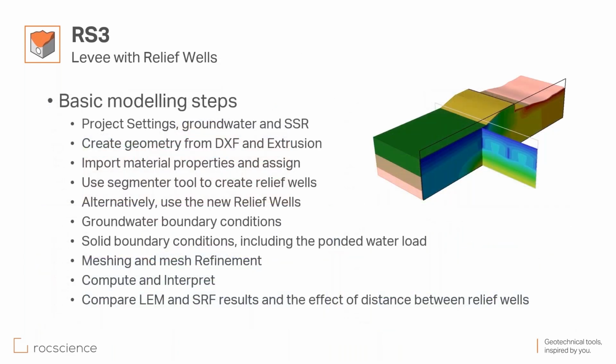These are the steps that I actually took to generate that model before, to analyze for seepage analysis. We will look at project setting, create the geometry, use Segmenter to generate those relief wells, or alternatively, I introduced the relief well entities that we recently developed in RS3. You assign your groundwater boundary condition, solid boundary condition, that includes the ponded water load. We mesh, refine the mesh if needs be. We compute, then we can take a look at the results.